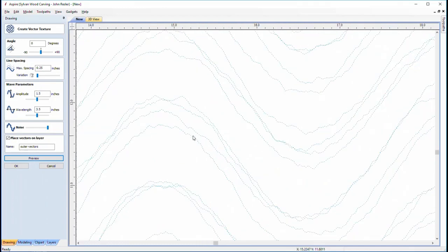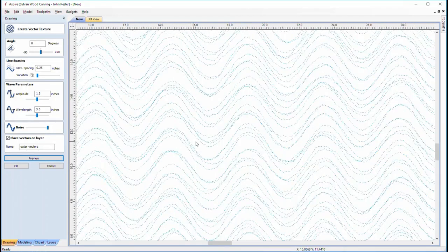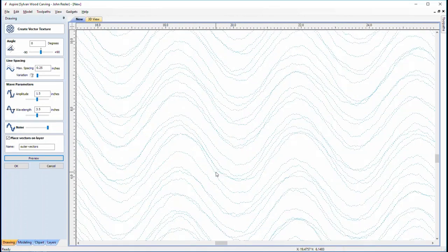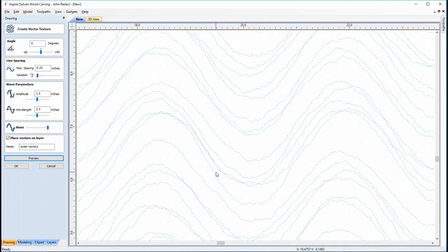And then if you look down in here, you're seeing a lot of erratic behavior moving back and forth between the lines. Now, I bring that erratic behavior up because if you decide that you want to do something like this, you need to remember that just because you're running lines across the length of the material, the erratic behavior is going to cause a lot of back and forth movement in the CNC. So what that's going to wind up doing is turning the duration of the cut up considerably. Okay? So that's pretty much how you do that.